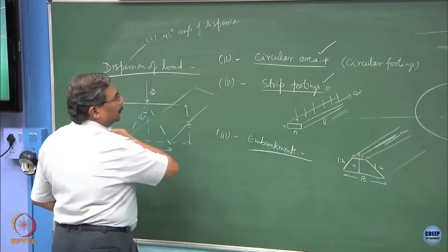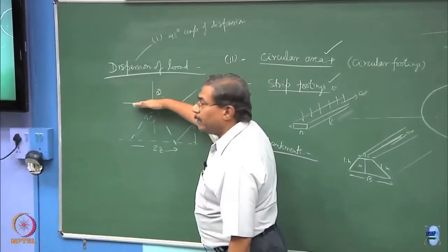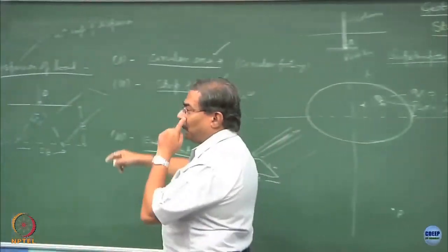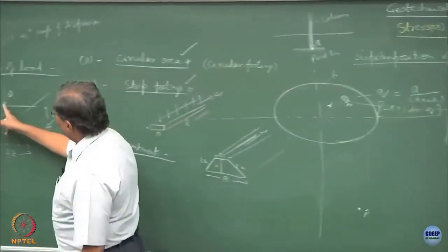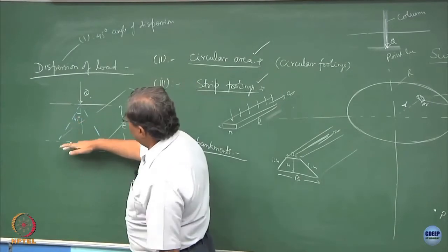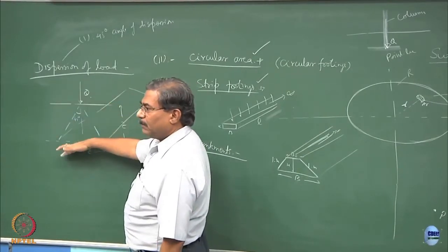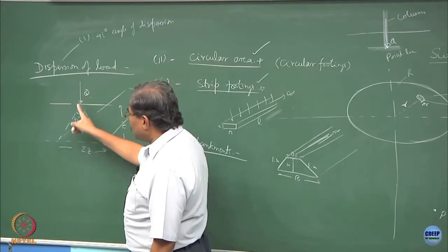So this becomes your loaded area. What I have done is I have delegated the stresses from this point to this point. So when you design foundations, normally we give a foundation pad. What this is going to do, I get 2-3 advantages. I have created a pad for the foundation system and I have reduced the stresses.